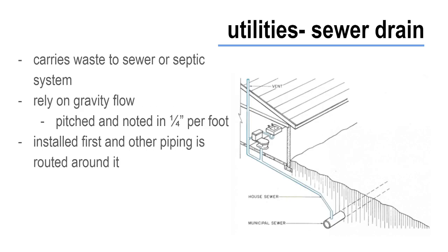So all underground utility systems must be coordinated also prior to installing your concrete slab, especially in commercial and industrial buildings. You may have a service entrance that needs to go into either sub-distribution sections or electrical panels. You may have electrical feeders coming in through different sections, and it requires detailed coordination between that electrician and the contractor, as well as the designer.